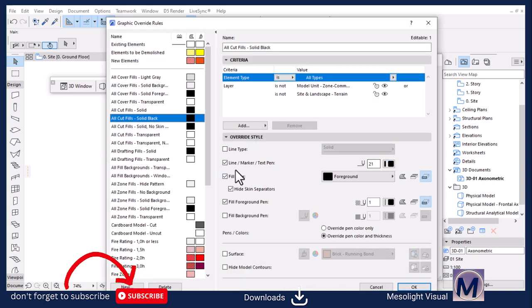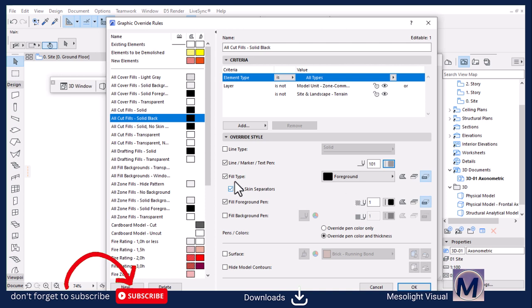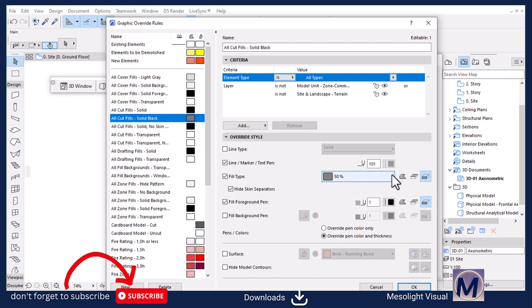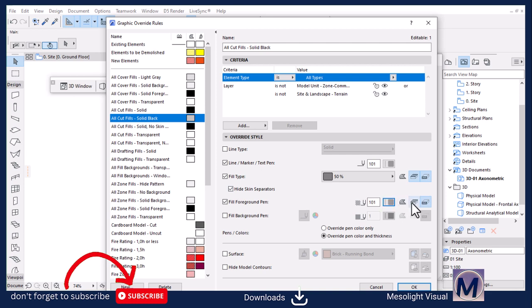Instead of having the line marker pen being thick or on 21 color pen, let's find a lighter pen, which is 0.18 grayscale, and the fill type should be around 50%, and it should affect all the override cover fields. And then the fill foreground pen is also going to be a lighter gray, and we're also going to affect the cover fill foregrounds, and then hit OK.